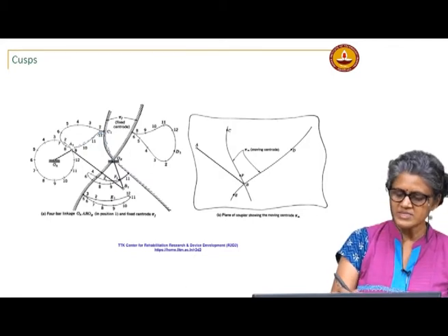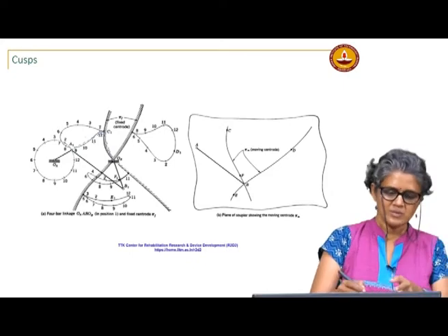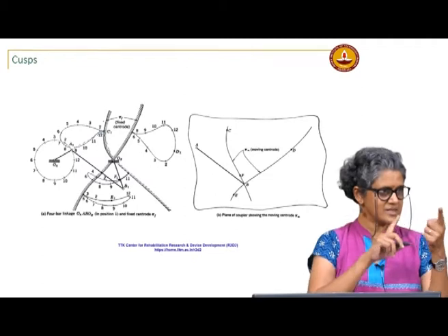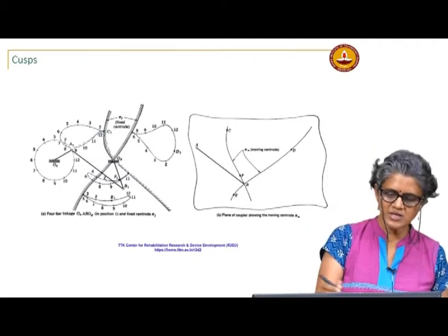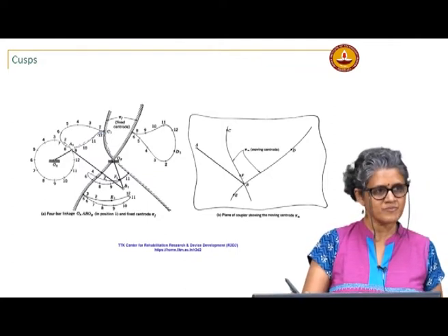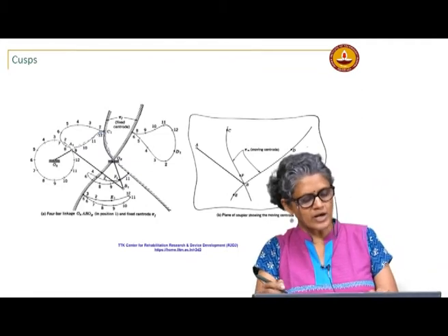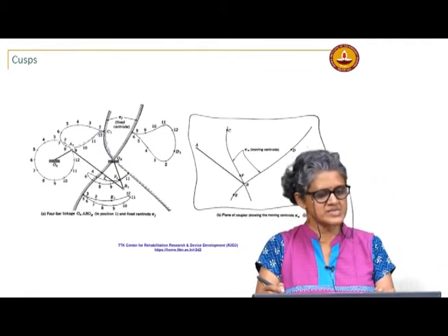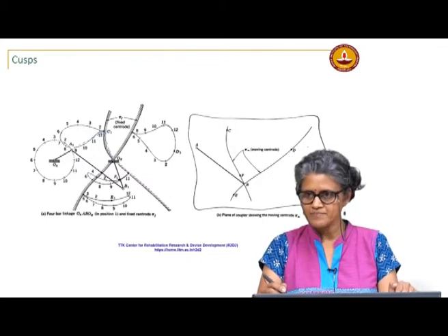These will hit at different other points, because at any instant there is only one contact between the moving centroid and the fixed centroid. These are other possibilities. So, points D, E, F also lie on the moving centroid, but they are going to contact the fixed centroid at other rotations of the crank.